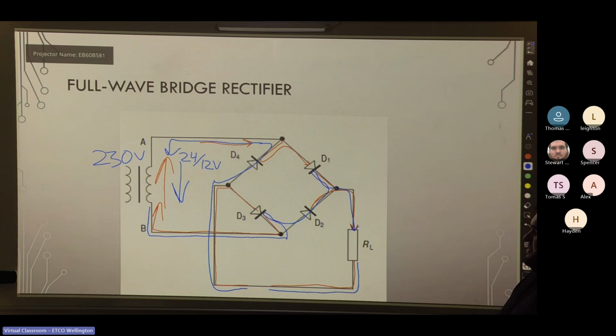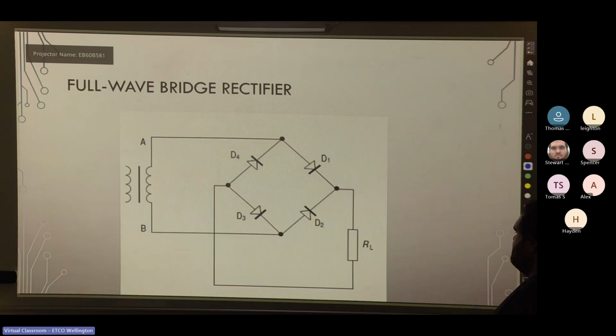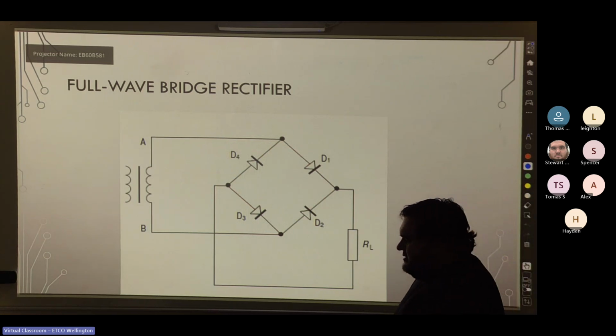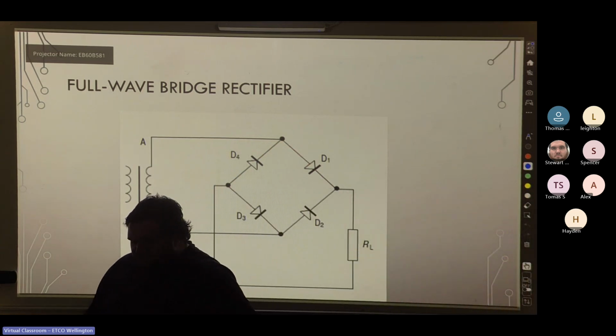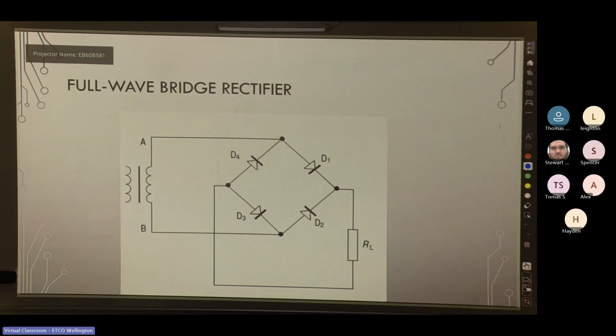So yeah, this usually more often than not comes up in the capstone. Not 100% sure on the digital ones, but I think last 10 paper capstones from back in the day had a question about a full wave bridge rectifier, just because it is the most common type of rectifier circuit you'll come across. So yeah, it produces a full wave rectified DC. It's a smaller and cheaper transformer, but it still requires smoothing. So usually it would be achieved by a capacitor and other smoothing devices.